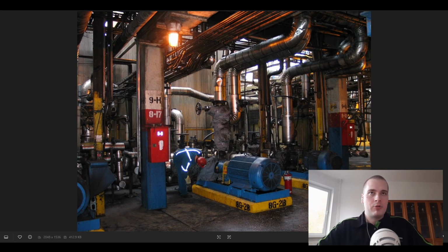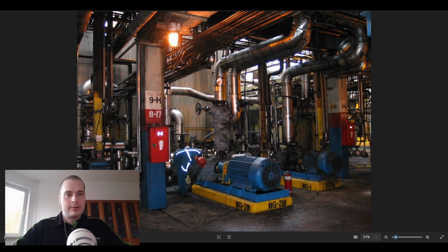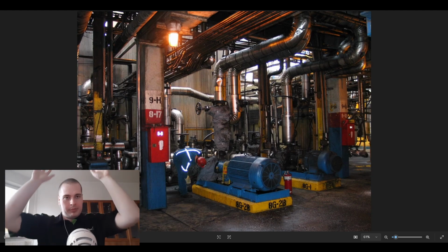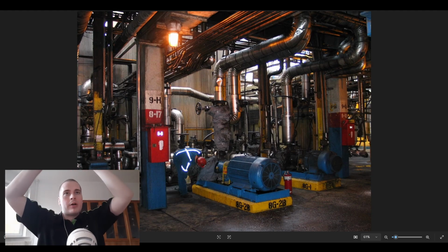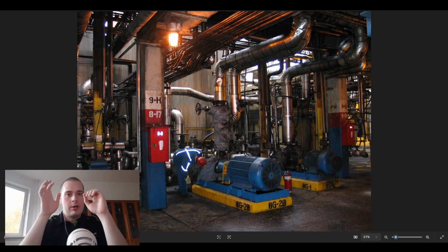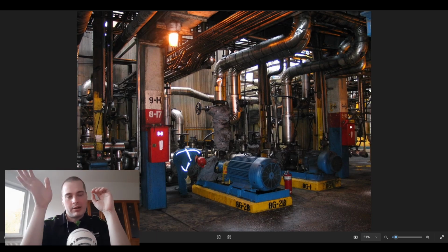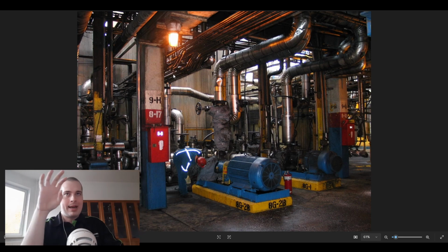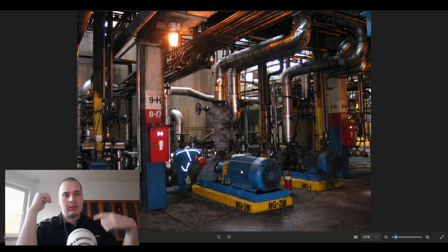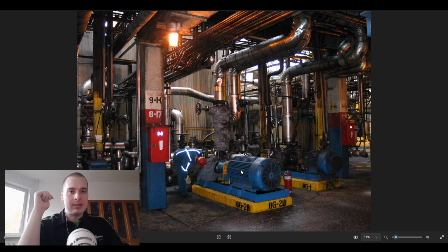I have another picture over here, and this was taken from under the piping rack. So all the pipes are above us and the coolers are above us, and we're looking maybe not exactly towards the area where the previous picture was taken, but what I think is at the back here is that amine storage tank we were talking about. And these two pumps, from what I understand, are the pumps that pump the lean amine into our high pressure and low pressure contactors.